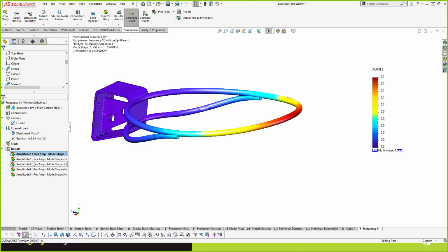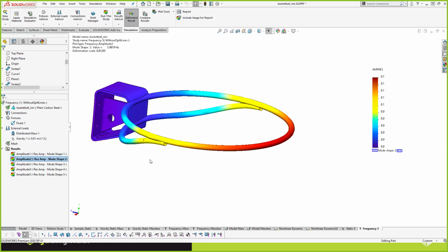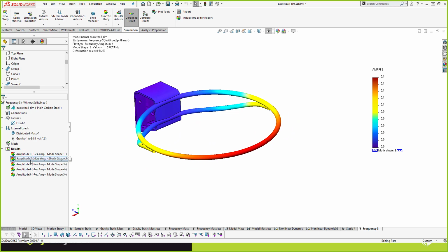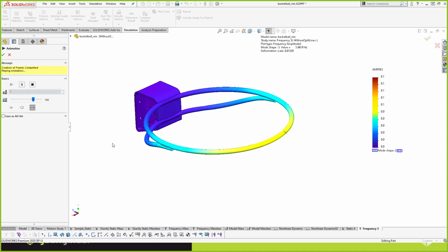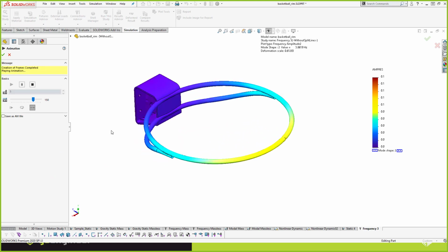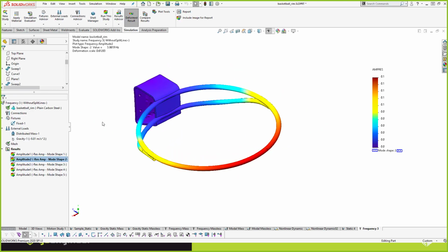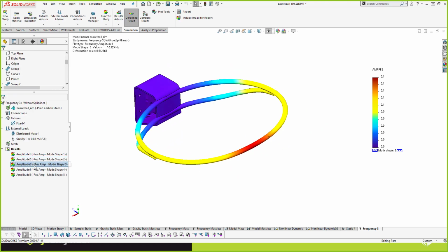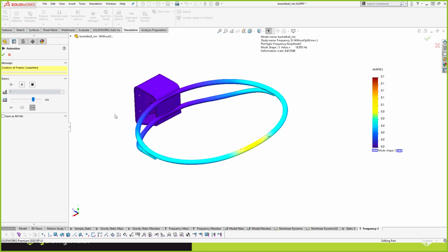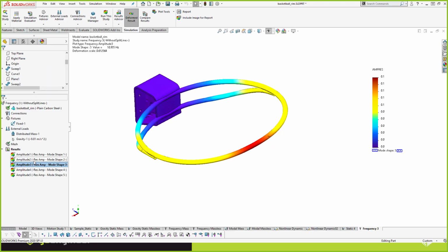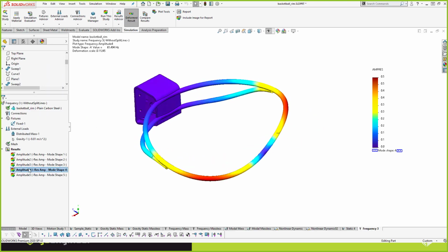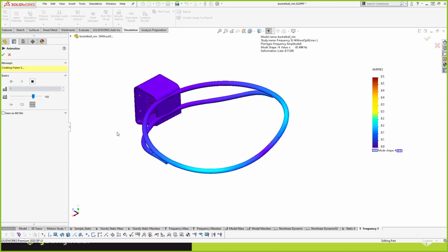But in addition to that, I can also look at some other mode shapes, ones that a hand calculation would have been a little trickier to provide me with. Maybe the side mode here, one that's going left and right. Now I don't expect this one to come into play because my load is primarily vertical. Another mode here wobbles in and out. This one happens at 10 hertz supposedly, and again, maybe this one might come into play a little bit, but not as much as mode 1. What about this fourth one though? If I animate this fourth mode, would this one come into play?